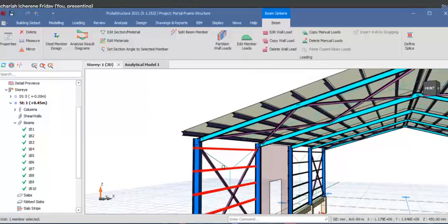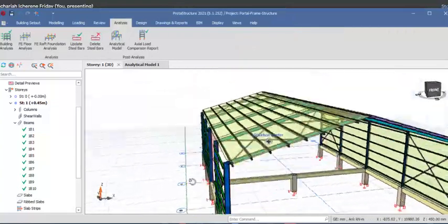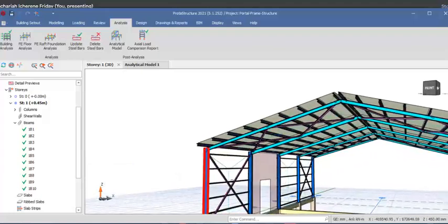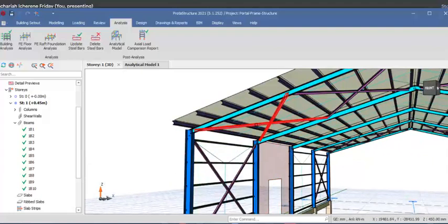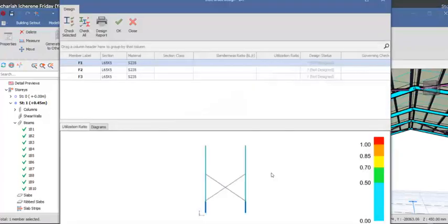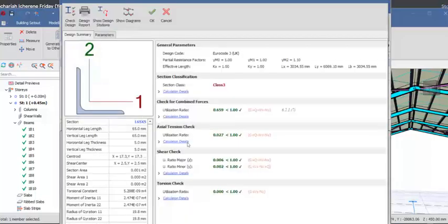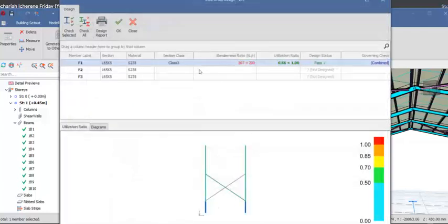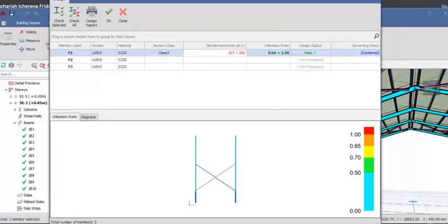Alright. So having checked that successfully, the next thing you need to check is the roof braces. So you can select that right there. Click on, still remember, design check. So you have this. So check it right there to see if it has passed. Okay, this has passed design successfully. The section has passed design. Click on the OK, and then you can see slenderness ratio. Okay, it is actually failing, but that can be corrected at site. Right. Okay. So click on the close option.